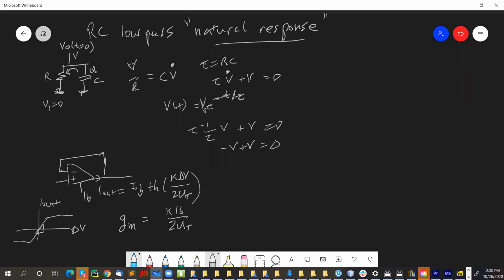So that's the transconductance, which is 1 over the equivalent resistance. So you see how this has units of conductance? It's a current divided by voltage times some constant. And again, it's subthreshold, so you just get back the thermal voltage. The only voltage that matters in subthreshold is this kT over q, right? So it's really simple. If you want a particular resistance, then you can compute what the bias current is that's needed to get that. Is that clear?